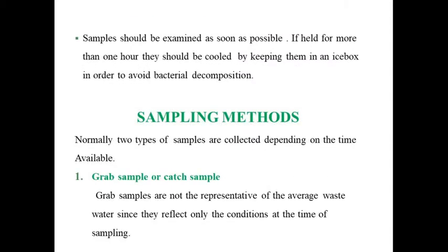The sample should be examined as soon as possible. If held for more than 1 hour, it should be cooled by keeping it in an ice box in order to avoid bacterial decomposition. As time goes on, bacterial activity, that is decomposition of organic matter, starts. That is why we need to check the sample as early as possible after collection.